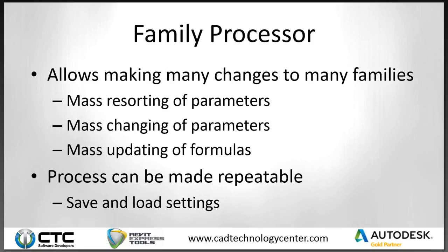This one allows you to make a lot of changes to a lot of families, as many changes as you want, modifying things like materials, modifying parameters, resorting them, modifying how their formulas are set up if that's important to you, and changing parameters from family to shared parameters. And the nice thing about Family Processor is that this is repeatable.